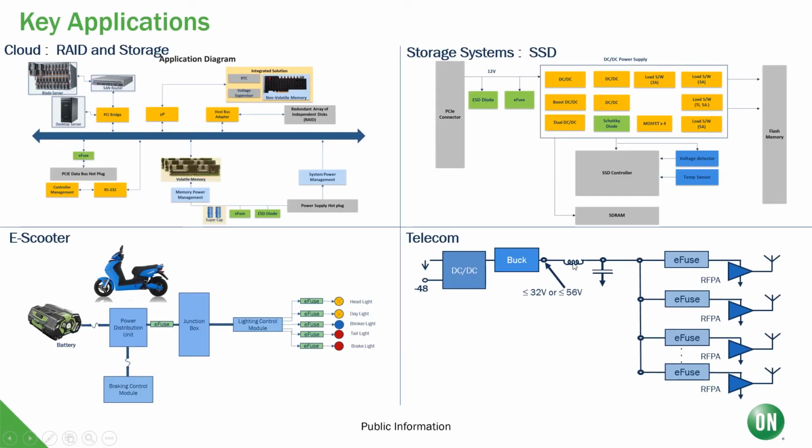eFuses are also required in RAID and storage systems as seen in the upper left. SSDs have additional needs for protection when it comes to the DC-DC converter as shown here. Also, we show e-scooters and e-bikes where they are used for different applications like the motor, lighting, and other auxiliary loads. Then there's 5G and telecom applications where you want to protect all the various RFPAs, which are ever increasing in number as we move into massive MIMO communication.